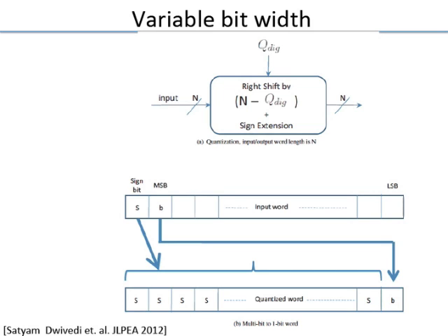So when you change the number of bits, what you are changing is what is called quantization noise. You change the amount of quantization noise you are using. And if you find that you can tolerate more quantization noise, you reduce the bit length. This is a simple way of reducing the bit length, where the input to the whole logic is right shifted. So then everything in the top basically has static values, and there is no switching activity.